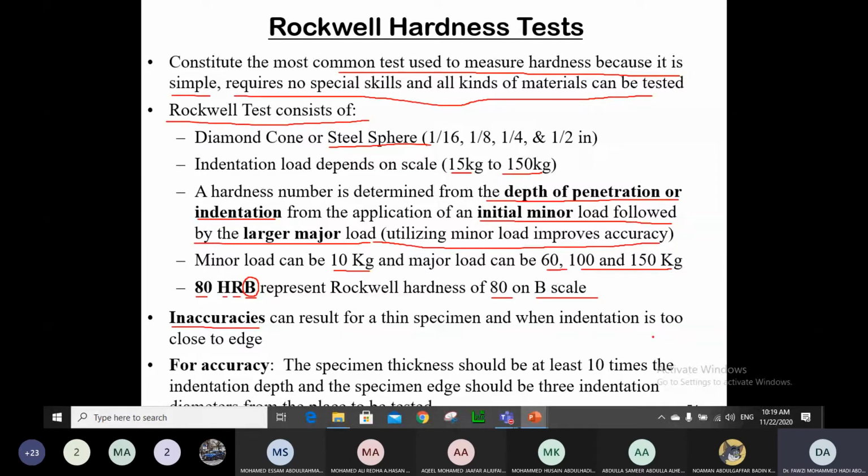For example, you could be having a thin material, and if the material is very thin, then when you are testing the material, for example applying the indentation on the side, you could actually be deflecting the material like this rather than penetrating the material or indenting through the material. So this is actually not a measurement of hardness. Therefore, you need to penetrate the material.